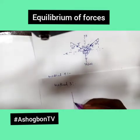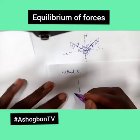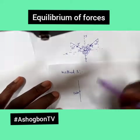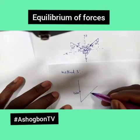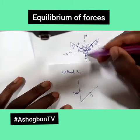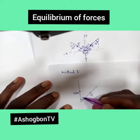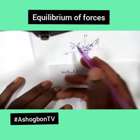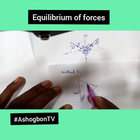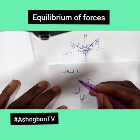So let's see. I have my weight somewhere here, which is 162 Newton. The other force here is actually going up. So what if I do it that way? It's going up, and that is T. Now if you check, this is in the direction of the tension and weight, isn't it? You will see that it's making an angle of 60 degrees with the weight. So I'll come here and put 60 degrees with the weight. Then look at this one, it is actually going this way, and it's going up. This is also tension. If you check these three now, you see that they are actually taking in order.